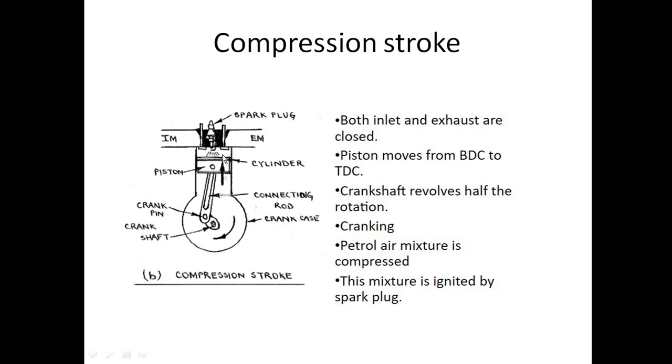At the end of compression, a spark will be produced by the spark plug, and due to that spark the fuel air mixture will burn, heat will be liberated, and pressure will act over the piston, which will move and produce power in the form of shaft power.